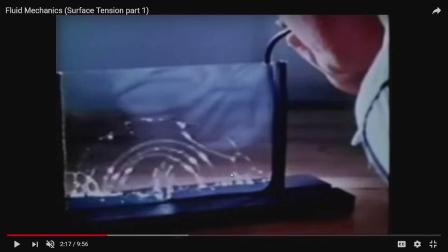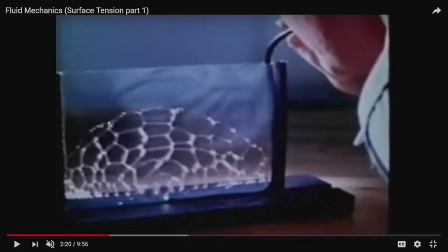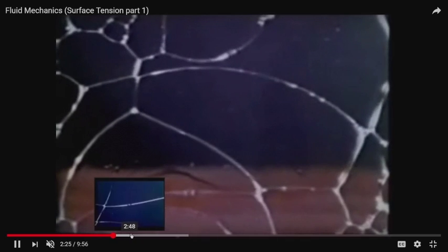Anyway, we were talking about simple devices or simple tests to help you understand your process. And I was mentioning that foam is a very common problem for industry, and this could propel itself into a foam meter. You have two glass plates that are separated by a very small amount. You put a little dab of your liquid in there, and you can photograph the behavior of foam, and you can detect differences possibly in foam using this device. You may not be able to put a number on it, or actually you would probably be able to put a number on it. Whether it has any physical meaning or not, it's another matter, but you can certainly rate the foam characteristics here. You have a lot of science going on here.